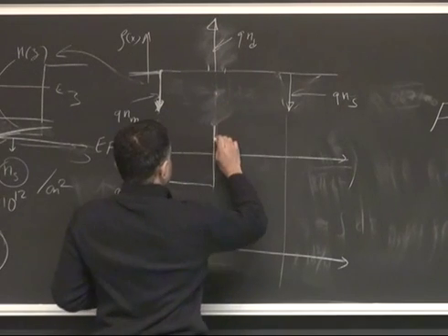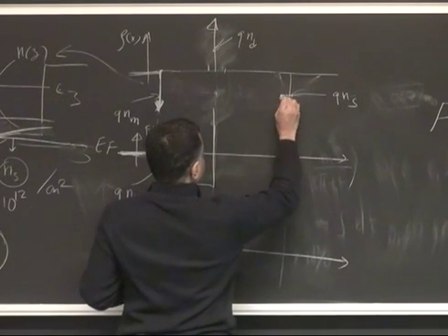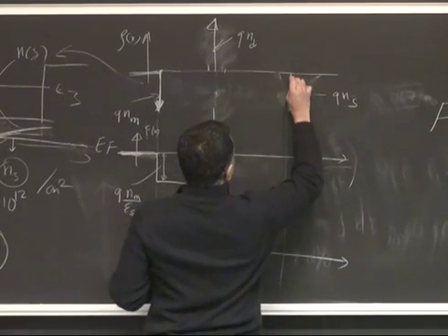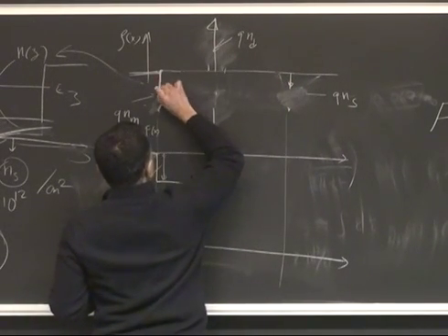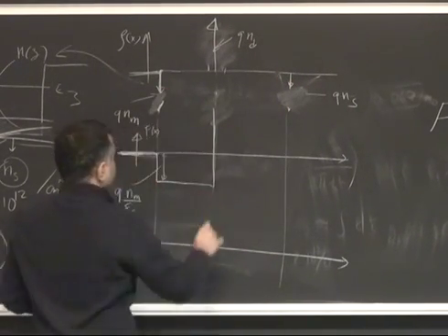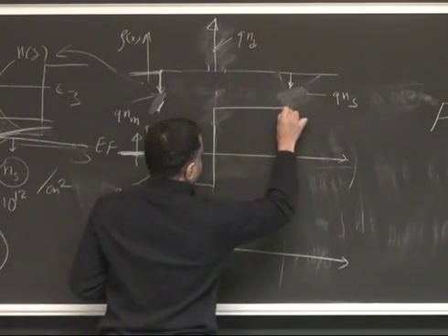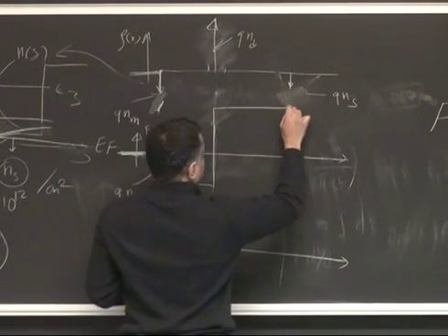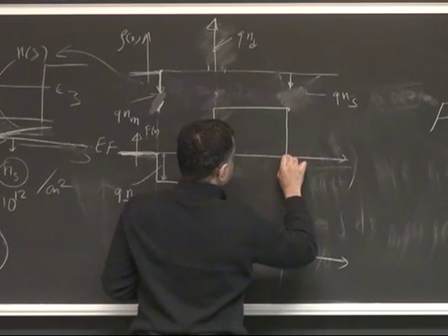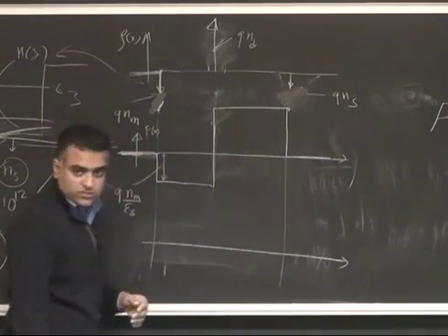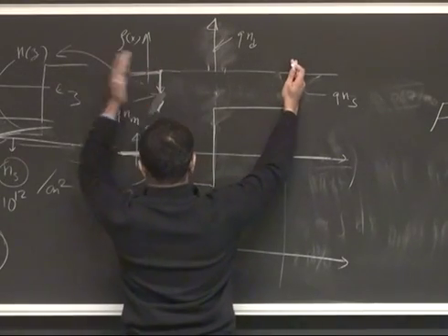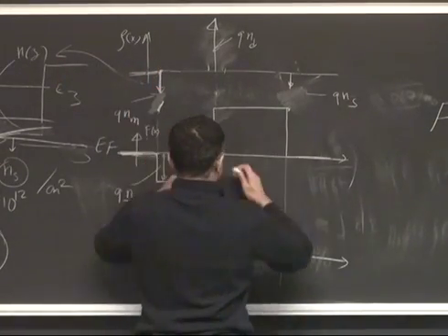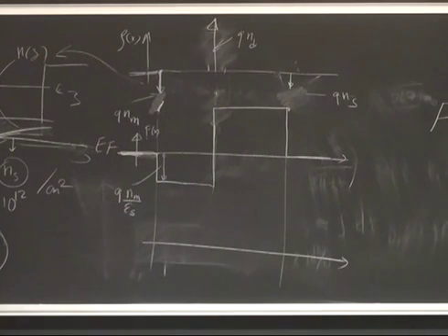And let's just, for simplicity, look at it this way. So this is 2E12, that's 10E12, and that's 8E12, right? So roughly to scale now. And then the field remains constant because there's no charge here. And then when you reach here, the field drops and goes back to 0 because the whole thing is charge neutral, right? This together is charge neutral. To the left is 0, to the right is 0, and this is the electric field distribution inside the whole structure.